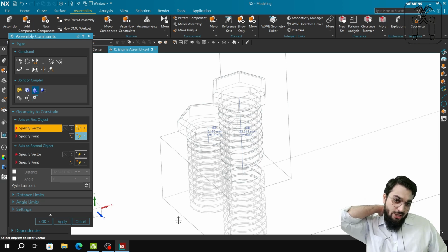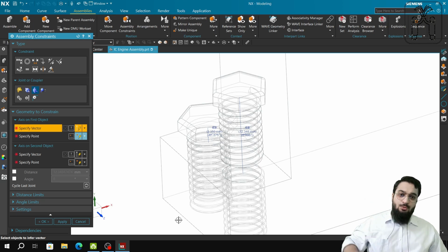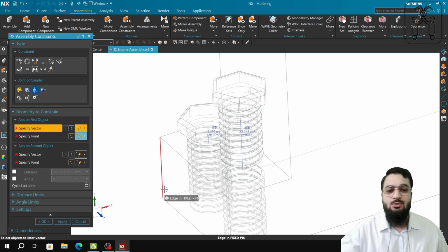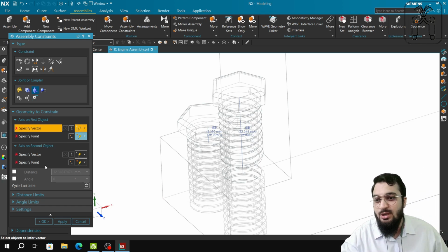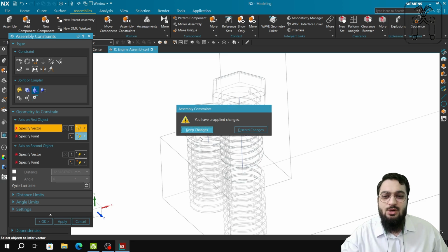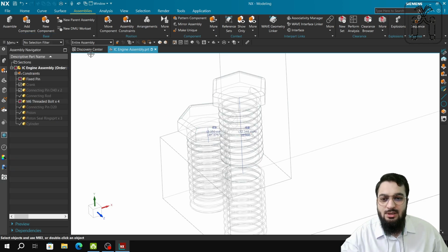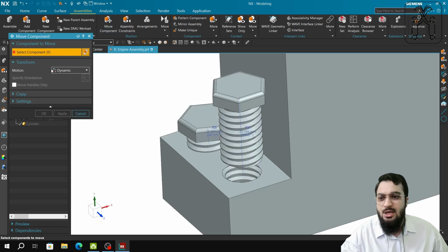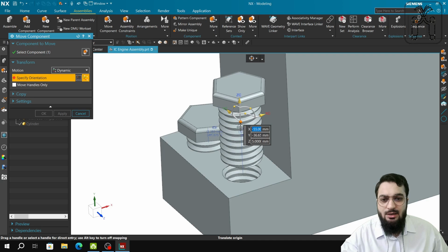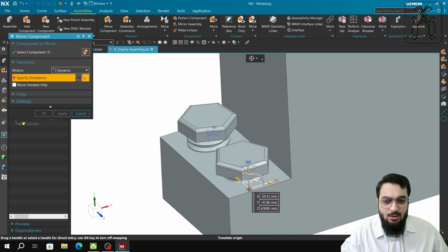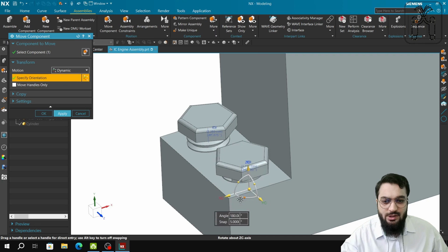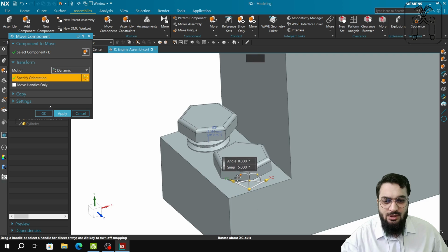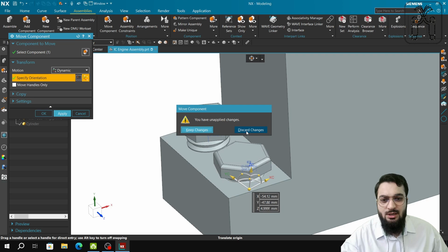If you take the vector opposite, the joint will be created opposite, so that means the bolt will be in the reverse direction. So nothing, you have to undo again and change the vector. So after that you have done that, you will see that this bolt has been constrained to movement in only one linear axis, and that it can only rotate in this axis, and it will not move, it will only move in this axis, it will not rotate. Okay, so I think that it is understood now.